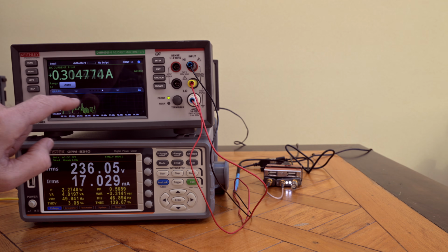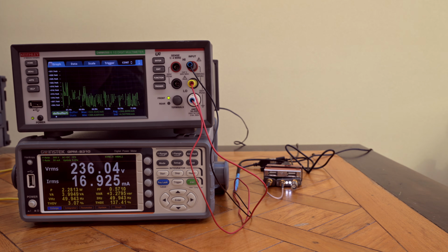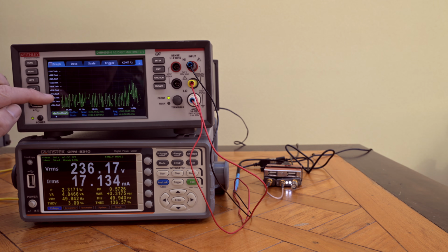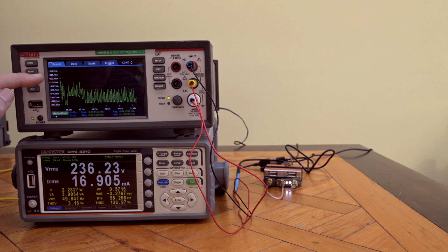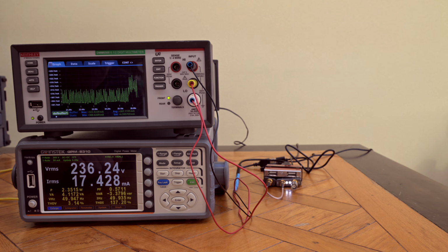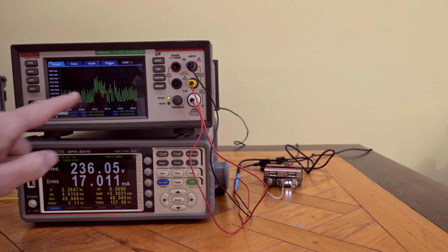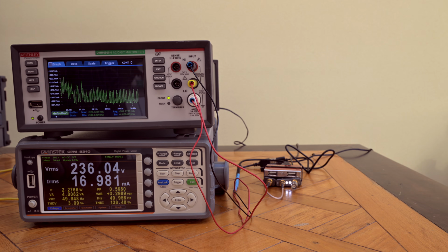Let me also go and look at the graph here. Yeah, and we see a bit of peaks here. The minimum seems to be slightly over 300, and it gets some peaks to a little bit more, 327. That's not an enormous difference. But we see that the power use comes with little peaks, and sometimes you get a moment where I think it's reading out a signal or doing something else inside. So power use is slightly more than I expected it to be for the unit, at least slightly more than what is advertised.